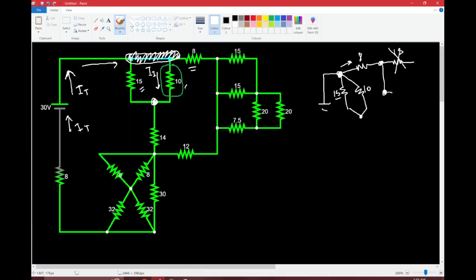Then over here they have an option of going through a 15 ohm resistor, which is this one over here, or they can go through nothing, right? There's no resistance here, so they're not going to go through this 15 ohm resistor at all. Then they come down here and they have the 7.5 ohm resistor, and they have nothing. And of course they're going to go through nothing, right?